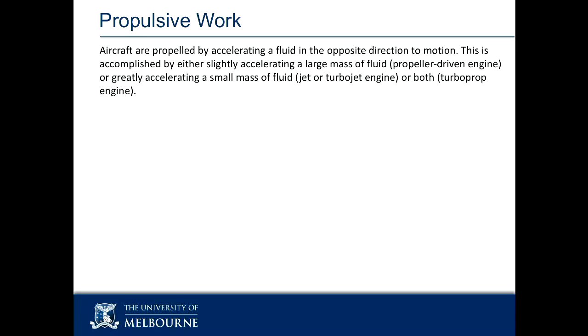And if you think about the job that a gas turbine is doing when it's a propulsion gas turbine, the turbine isn't connected to anything else outside of the machine. It's only connected to the compressor. So in a propulsion gas turbine, the turbine's only work output is to run the compressor. And the extra energy that's left over in the enthalpy of the working fluid gets converted into velocity. So that's where we use that nozzle to maximize the velocity of the gases coming out the back.